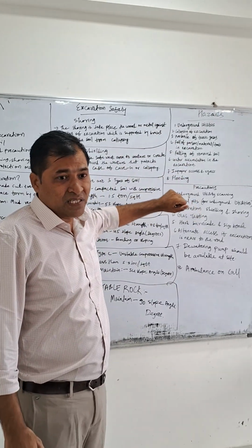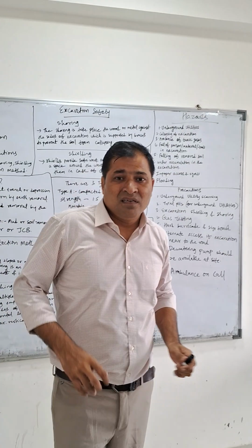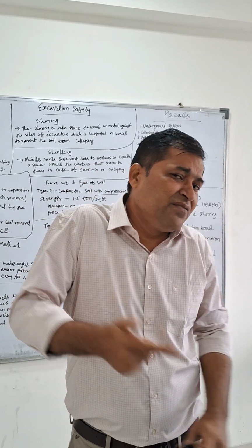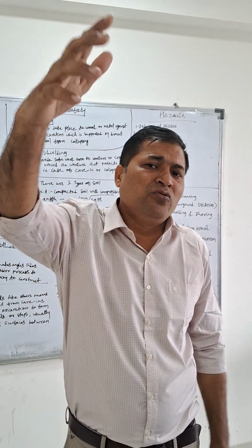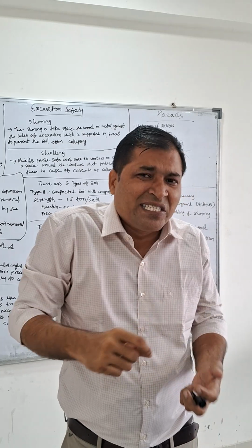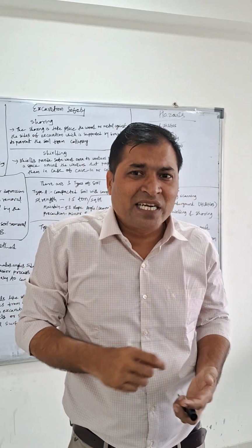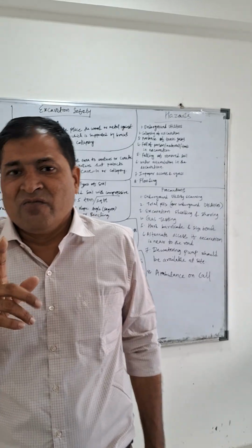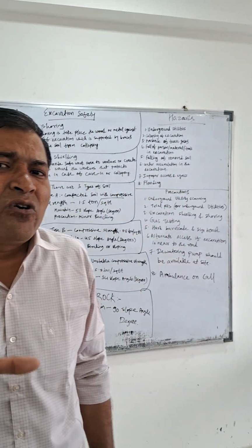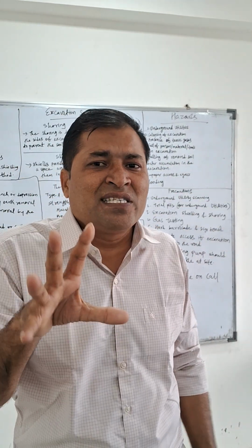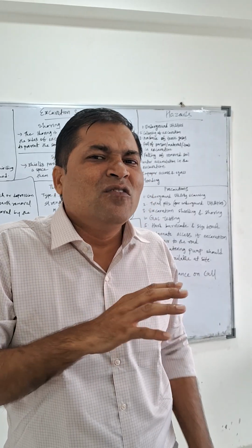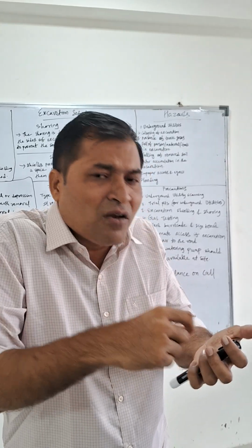Now we'll come to the hazards. There are different kinds of hazards over there in the excavation work areas. So you need to go with the inspection checklist, fill the inspection checklist, and go with TBT, toolbox talk, with your team. Toolbox talk is very important. Whatever hazards you come across, immediately report to your seniors, report to the supervisor, and follow the checklist. Fill all the checklists.